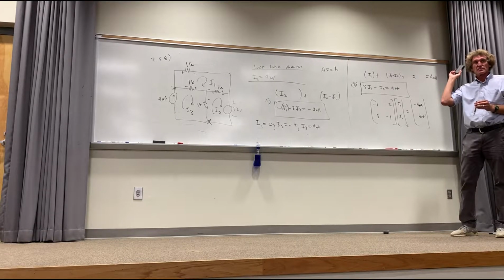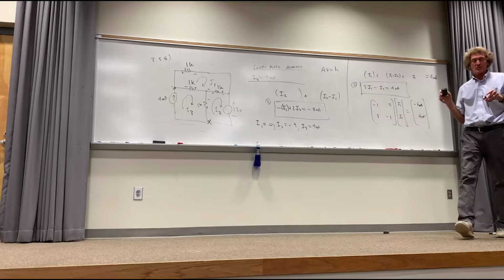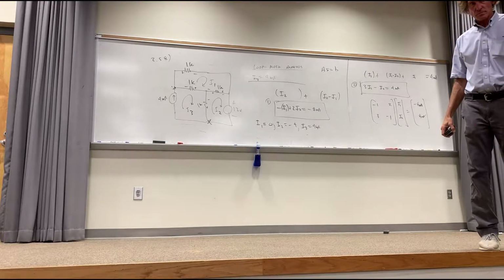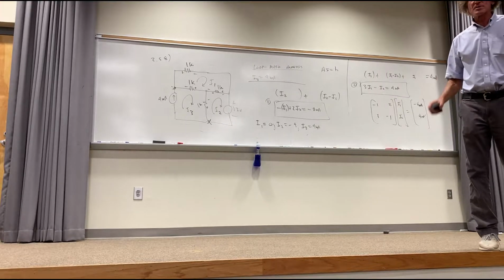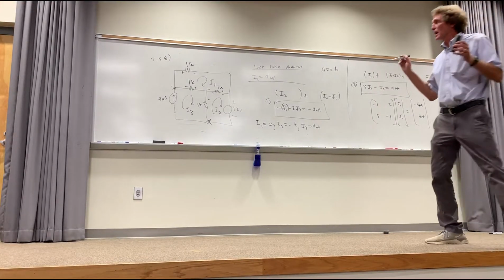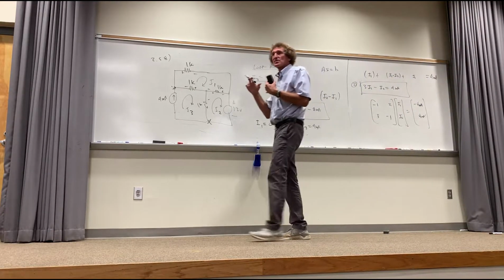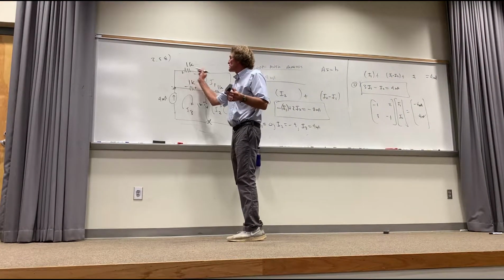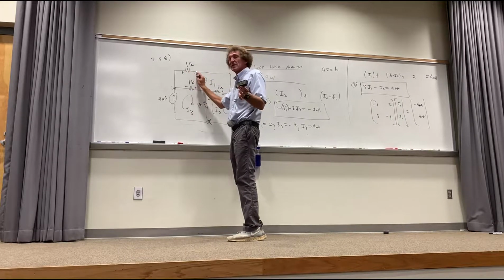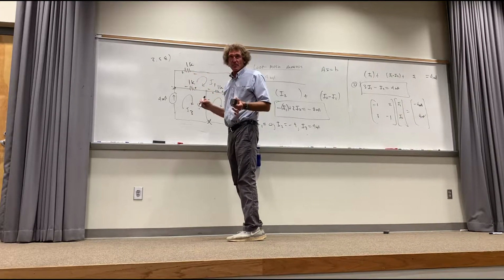So for this problem, when it comes to the polarity of the resistors, is that arbitrary? No, resistors aren't polarized. This is the polarity of the voltage drop. I always do this, I take everything as a drop through a resistor. That means I need the net current into the terminal I label as plus. You go from a plus to a minus, around summing, it's a drop, it's minus.